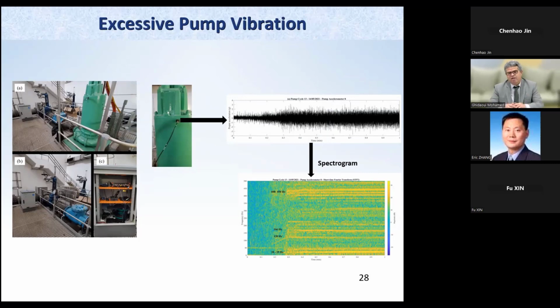it's vibrating. This is one location of measurement in a couple of kilometer pipelines. And the reason we can do that is because these waves travel at about 1 kilometer per second. So that means a 2-kilometer pipeline, you could sample in about 5 to 6 seconds. And so these are really almost as quick as your ultrasound in the medical business. But of course, here we're going further because this is long range.